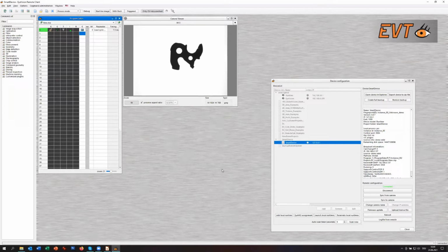So to have a feeling if your solution works on the smart camera, you can simply have a look at the timing at the end and see if you are as fast as your process needs. From our experience, if you do the standard gray and color image evaluation, up to 10 parts per second can be done with smart cameras, depending on the instruction set you need.